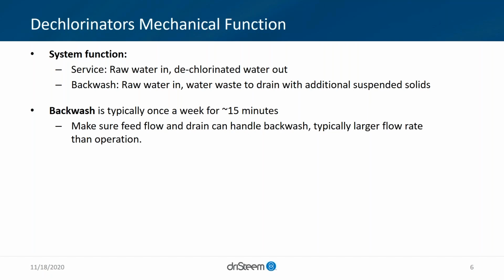Backwash, again, is simpler than a softener. It's one cycle that it goes through. It's typically about 8 to 15 minutes, depending on your site conditions. So what that backwash is mainly doing is reversing that flow, lifting that bed up, and removing any fines or suspended solids on the top of that bed. That's very important for the sake of the mechanical system. The more solids you have on top of the bed, the more restriction in your system. And really, if you choose not to do it, that restriction can build over time and you can have dynamic pressure issues.